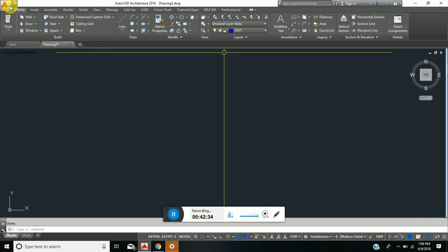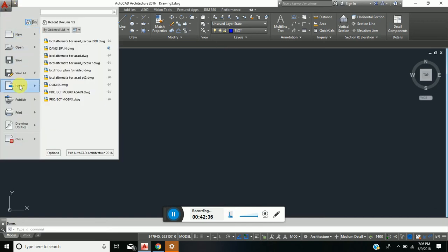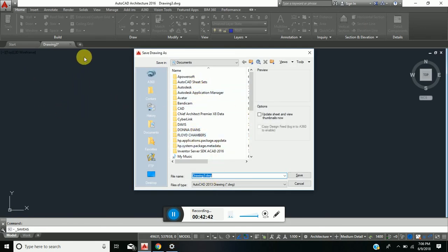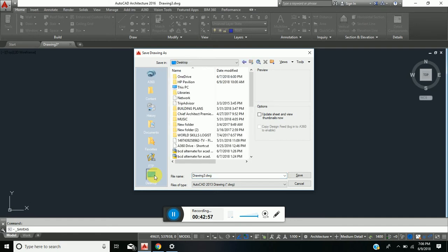like we save a drawing, we go save or save as preference. So we go save as, and you determine where you would want to have this template saved, because it could also be saved as a feature of AutoCAD in the template system. I'm going to go ahead and save mine on my desktop. Alright, and I'm going to be giving this a file name, let me call it Mark ACAD.